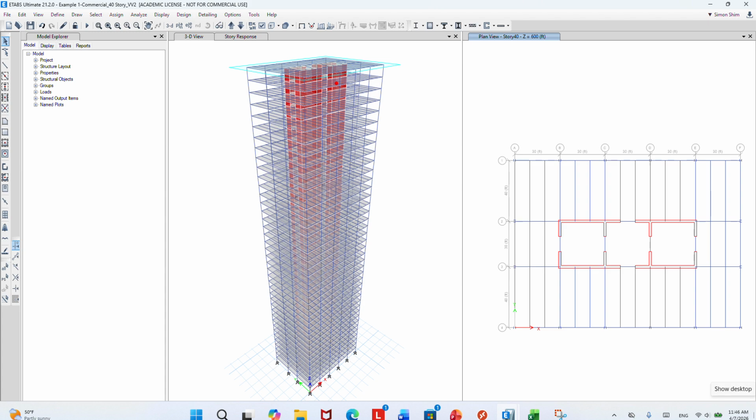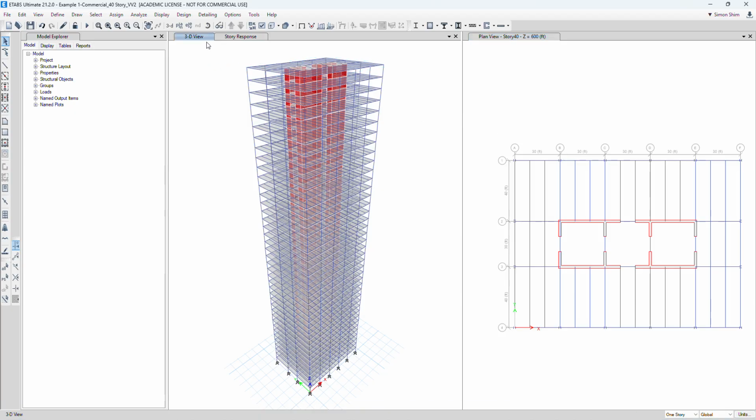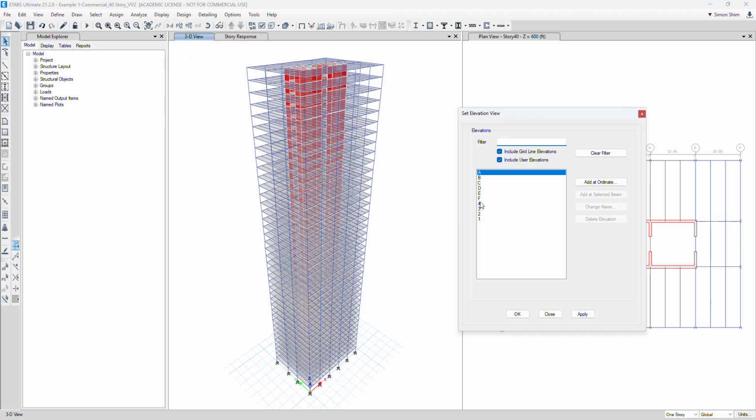So here, I'm gonna add a truss first on this line and this line, in a more symmetrical way, right? So that avoids any torsion. So my case, your case is maybe different, but by looking at mine, I have grid lines B and E. I'm gonna choose and add the outrigger truss. B, I'm gonna choose elevation B.